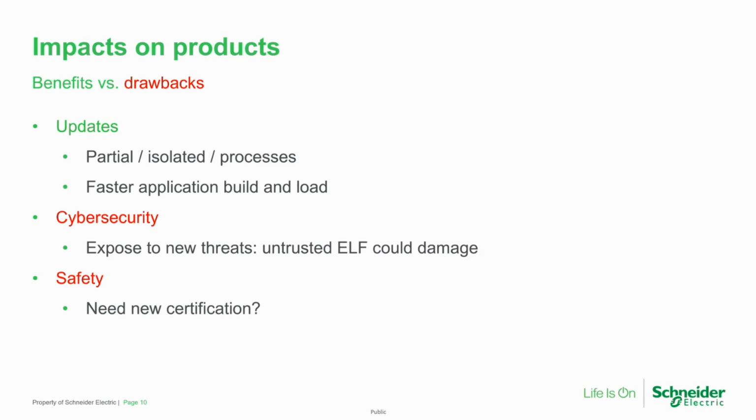You can say, okay, since my base firmware is the same, the validation is still okay. I just need to focus on the LLEXT extension and check that I have no problem with that. So you decrease a lot the piece of code that changed, and you decrease a lot the impact of it. So as an initial step, we have to do what we call an impact analysis. We go much faster with LLEXT.